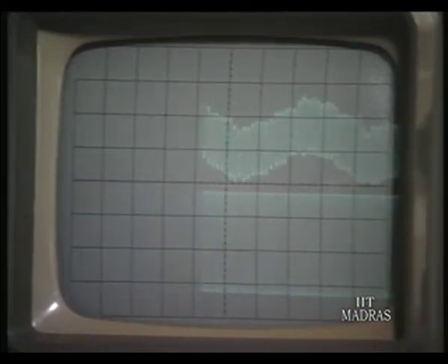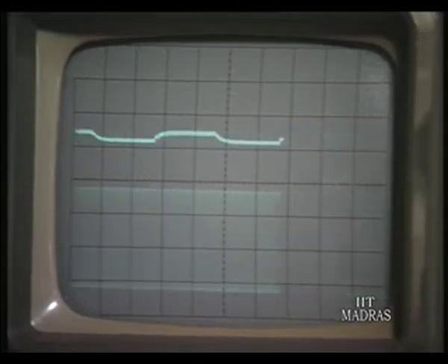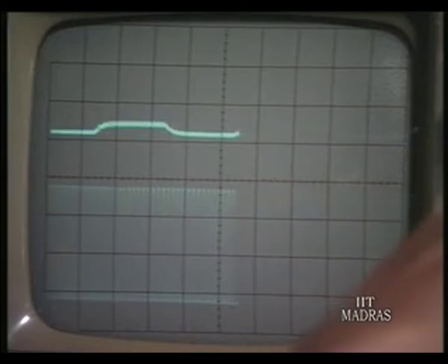Now, what we are doing is synchronous detection. The output of the modulator is fed to another multiplier, and this is now fed to a sort of low pass filter, so as to eliminate the high frequency component, and you can see this, the output of the multiplier now contains the carrier also before filtering. You can see the square wave, and then the filtered output. This is the filtered output. Increase the scale please for the filtered output.